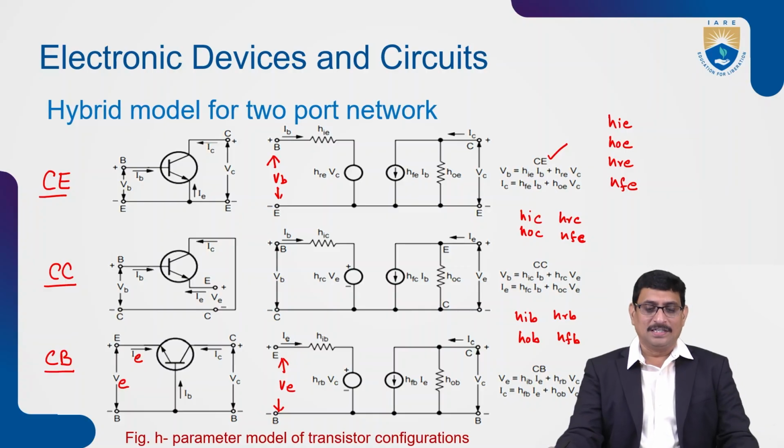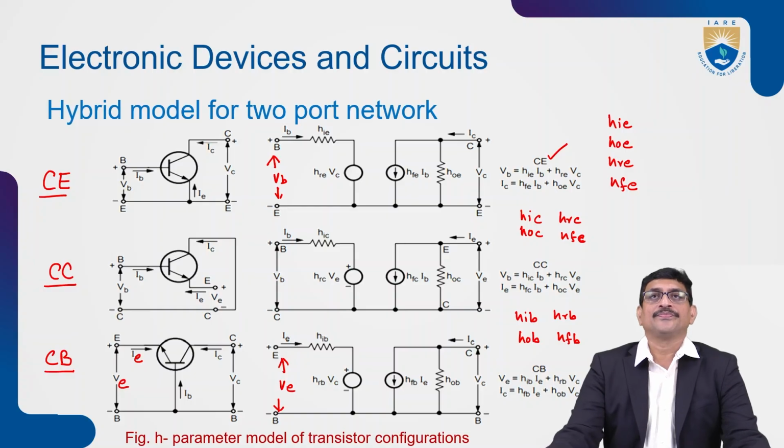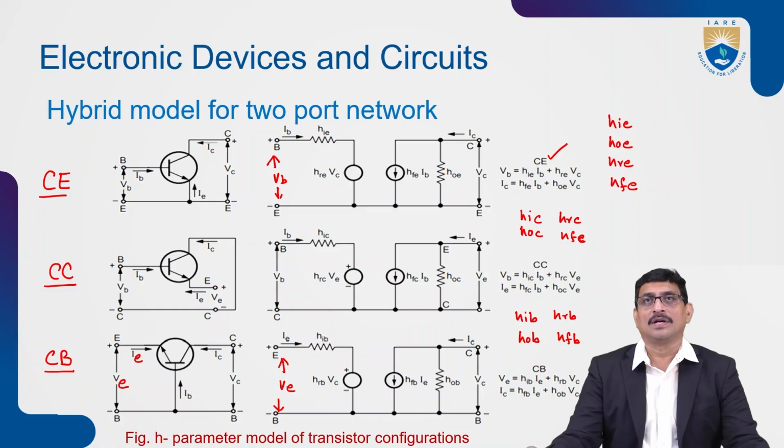Right? So, dear students, in this session we learned what an amplifier is and where the operating point is to be chosen on the DC load line to get a stable operating point, and with respect to that, the condition we need to use for thermal stability.